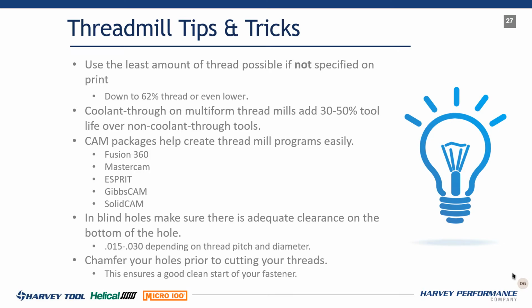And chamfer your holes prior to cutting your threads versus after. This ensures a good, clean start for your fastener. It's just common practice. Chamfer all your holes. Go in there, drill your holes, chamfer your holes, go in with your thread mill.